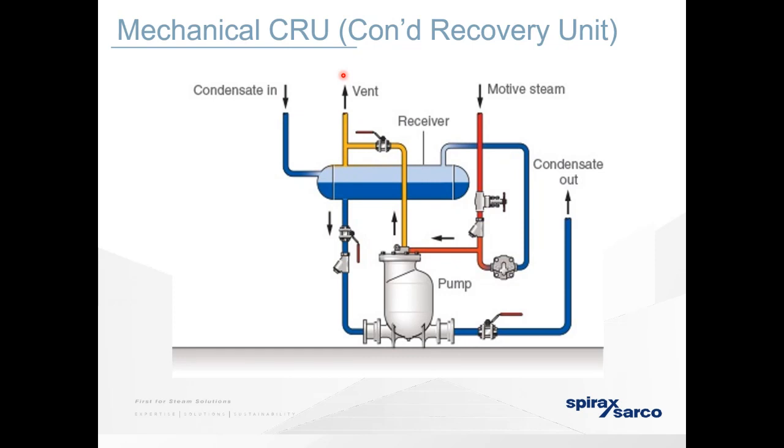Yeah, for true losses, you'd also need one on your blowdown, your TDS, wherever that retains, because then you're seeing what you're producing, what you're having to dump, and what's returning. So effectively, you could work out the value for money and the percentage of return that way. But you would need a meter on both sides.